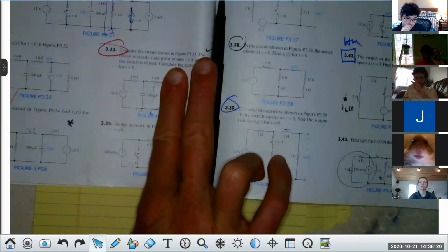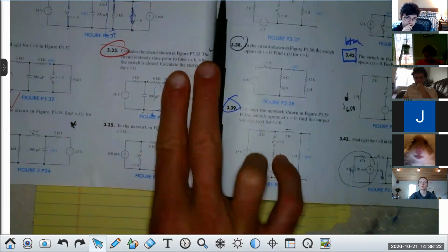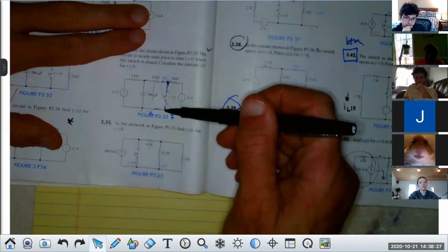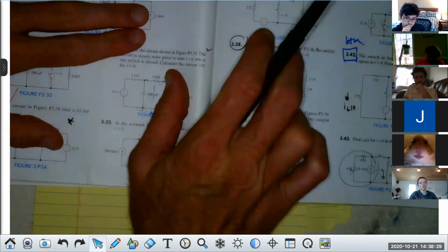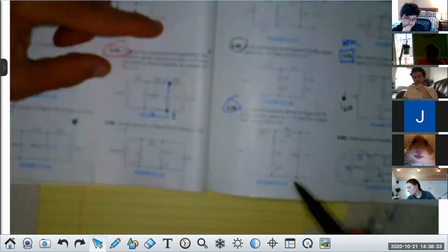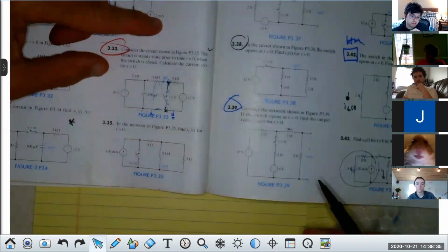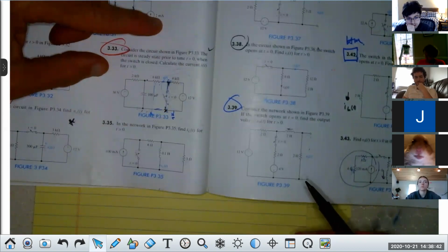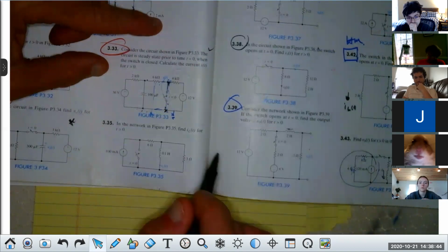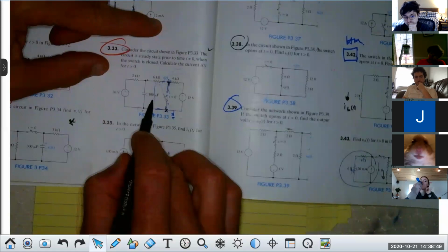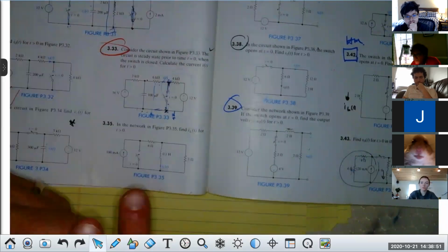Kind of. Well, what don't you see, John? When this thing switches and closes, you see how that point is that point? If that point is that point, can't I take that 6K and just bend it and connect it here if I want? Isn't that in parallel with the... I see what you're saying now. If you see that, then you know the voltage across that capacitor is the voltage across that 6K, period. And if I wanted the current through the 6K, I would just take the voltage across the capacitor divided by 6K. You all see it?